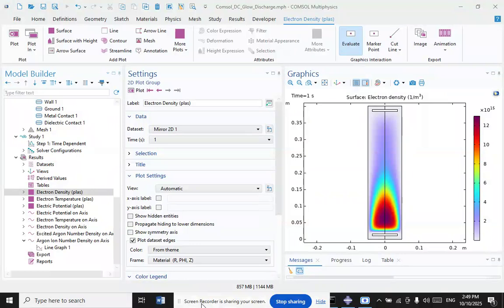And what about the secondary emission? Some of the ion's kinetic energy is transferred to the cathode. This happens partially through the ions striking the cathode directly. The primary mechanism, however, is less direct. An ion strikes the more numerous neutral gas atoms, transferring a portion of its energy to them. These neutral atoms then strike the cathode. Whichever species, ions or atoms, strike the cathode, collisions within the cathode redistribute this energy, resulting in electrons ejected from the cathode. This process is known as secondary electron emission.